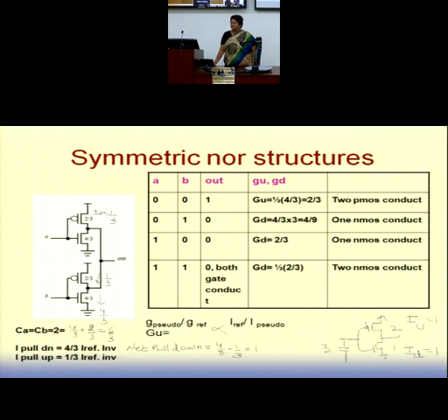Okay, so now if both are 0, 0, both PMOSes are on. My standard inverter is this. My standard basic gate is this one, designed in the ratio of 2:1, and they are designed such that their drive currents are the same. So I can take both to be equal to the unit: I up corresponds to 1, say, and I down also corresponds to 1. Let me assume that. They have the same drive.